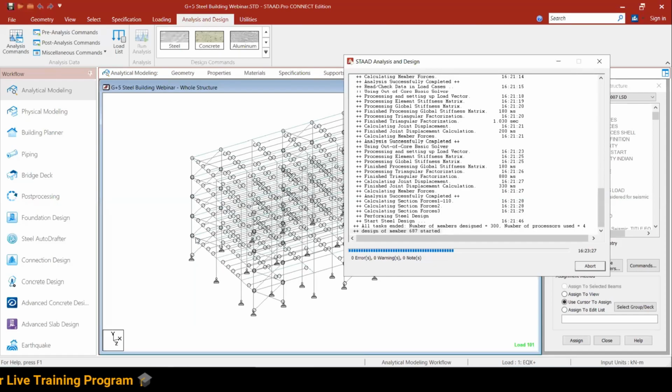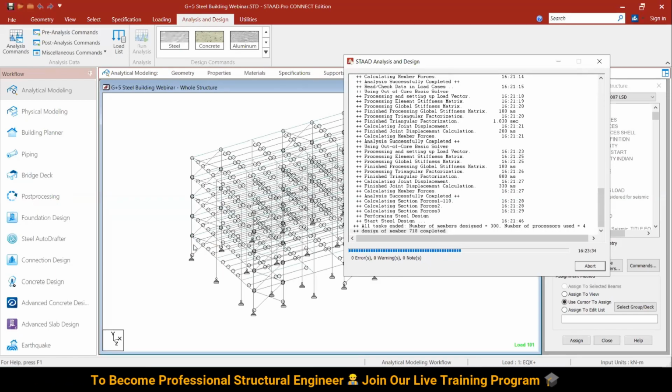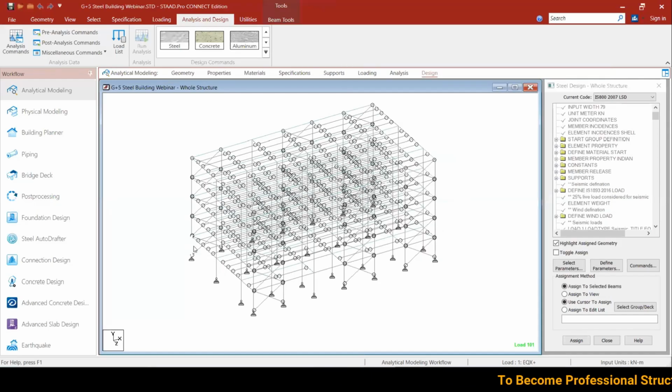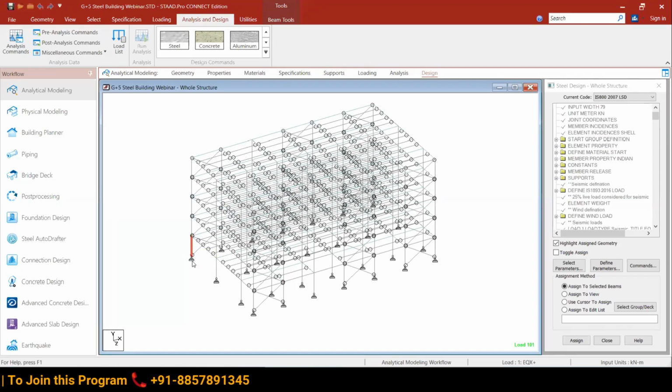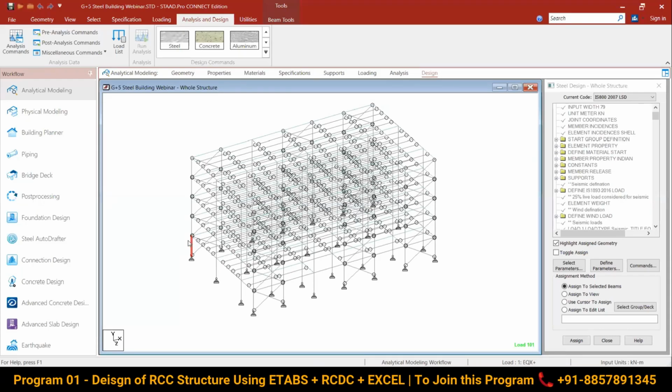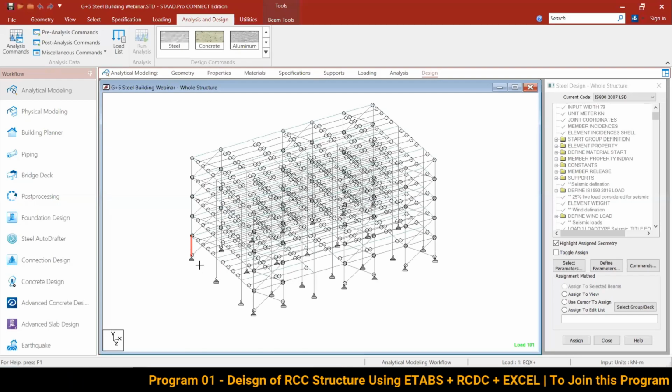If in the other directions I have these bracings, then for LY, where we have these bracings, we can break the member. But in my case, for both directions, LY and LZ will be 3.3, that is the height of my structure. And KY, KZ will be 0.8 because one is simply supported and the other is fixed. So based on my support conditions and depending on my height, those values generally change.